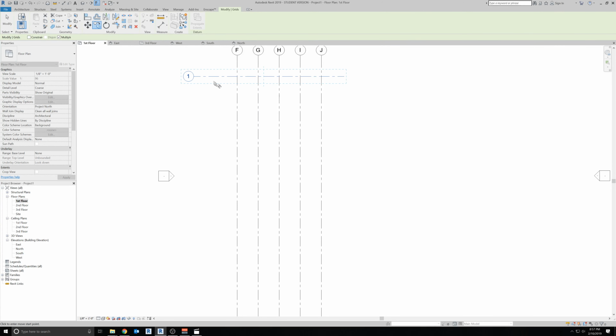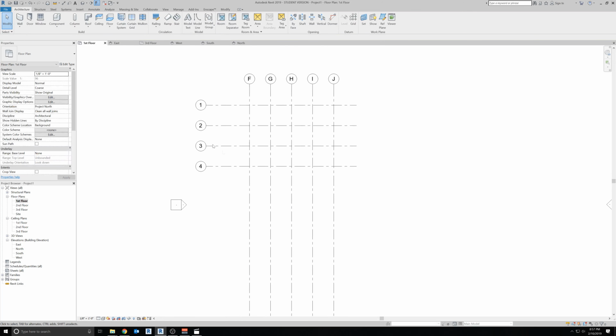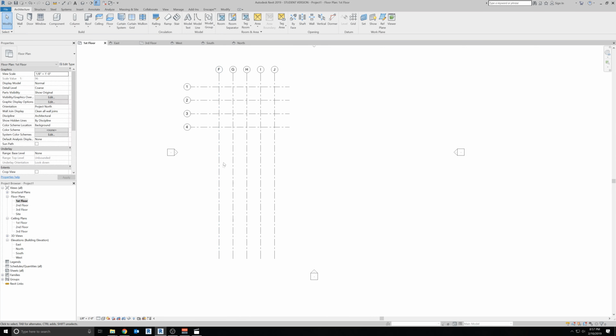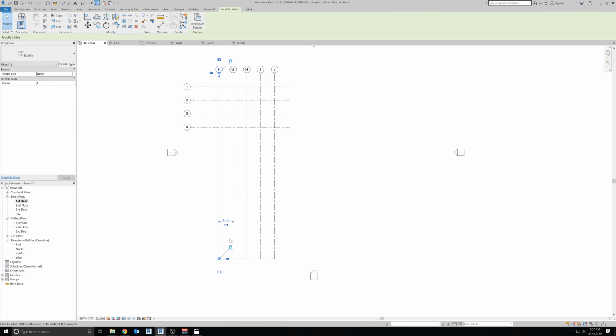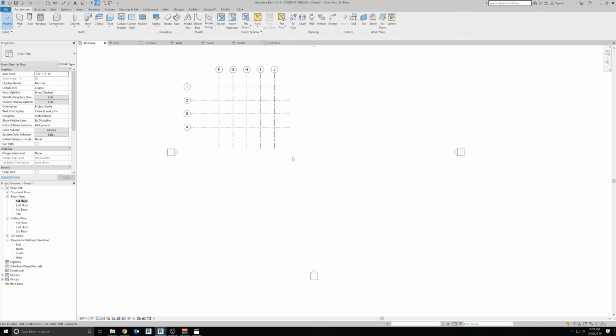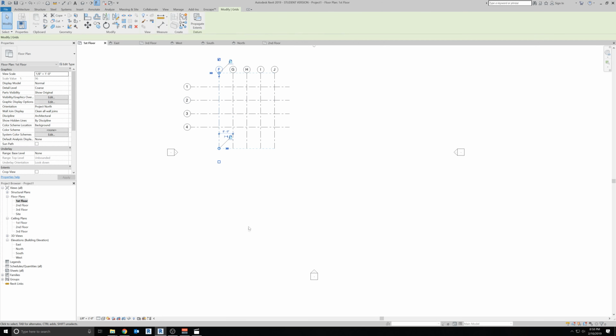So again, now instead of creating all the grids, I can just copy grids. I make sure that here I have multiples, and I go with 8, 8, 8, and really easily Revit already knows that it's gonna be numbers. Now, the same thing we saw in elevations applies in plans. So if I bring this up, it will be up also on the second level. But if I say 2D, it changed only on the second level and not on the third level.